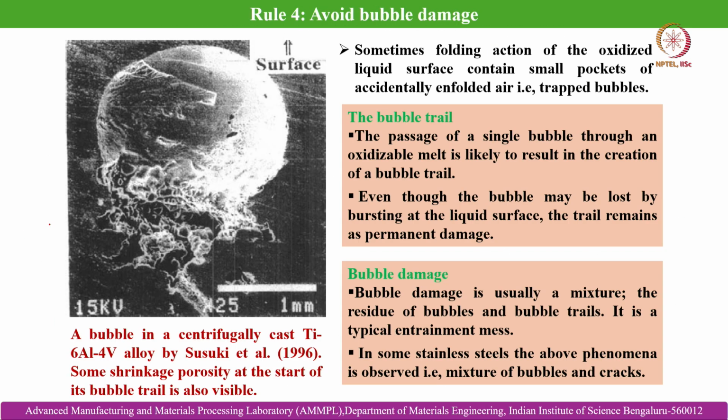So, then rule 4, that is to avoid bubble damage. Sometimes the folding action of the oxidized liquid surface contains small pockets of accidentally enfolded air, that is, trapped bubbles. Bubbles can originate from different regions. Please recall that in the previous classes I have discussed the several sub-sections of a mold cavity in casting. When we discussed the sand mold, we also discussed